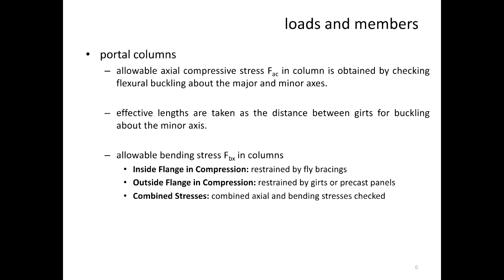And the same thing for the rafters as well. The rafters have a series of purlins, so thereby the effective length becomes the distance between the center to center of the purlins. So it's the same concept. That purlin prevents the entire rafter from buckling as one, rather than buckling in between the purlins, if that makes sense.